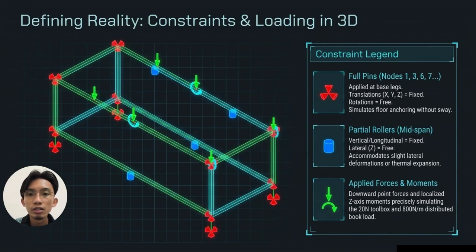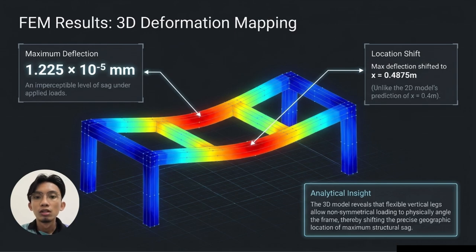After creating the geometry, the structure was divided into smaller finite elements through meshing. The mesh allowed the software to calculate stresses and displacements throughout the structure. A suitable mesh density was selected to achieve reliable results while maintaining computational efficiency. This slide presents the stress distribution obtained from the finite element analysis. The highest stresses are concentrated near the frame connections and joints where the loads are transferred between members. This location experiences greater stress due to the interaction between horizontal and vertical frame elements.